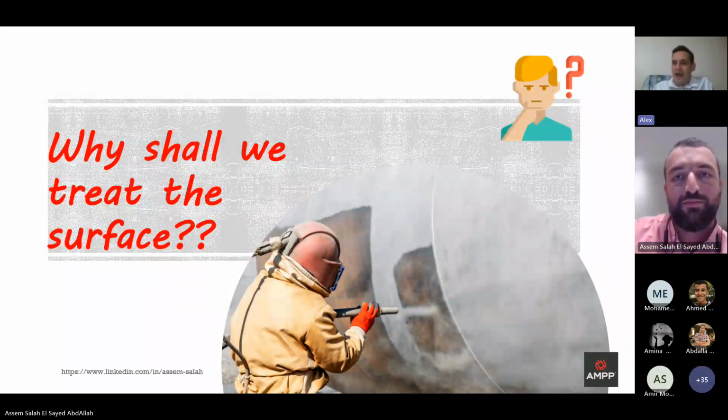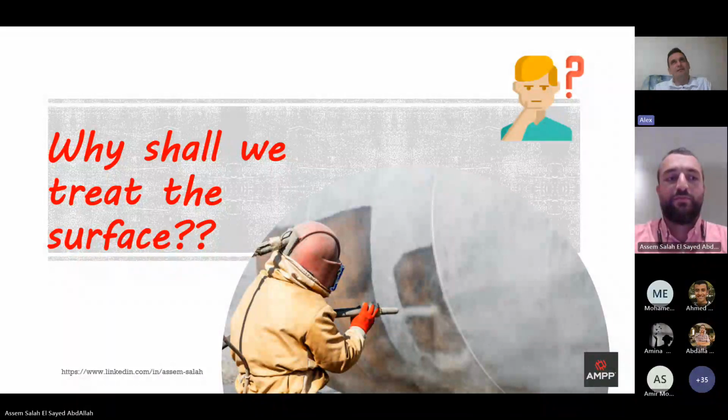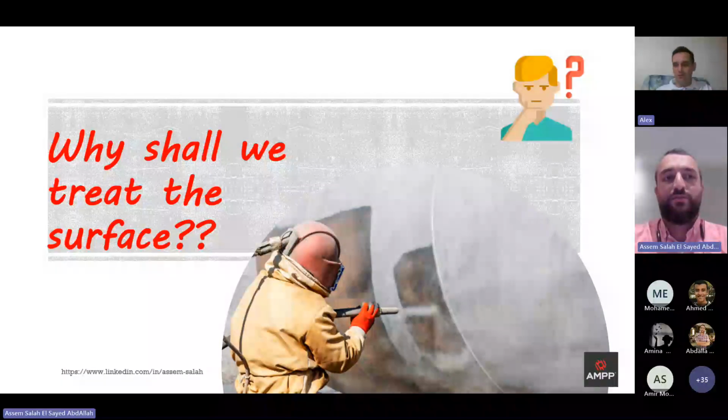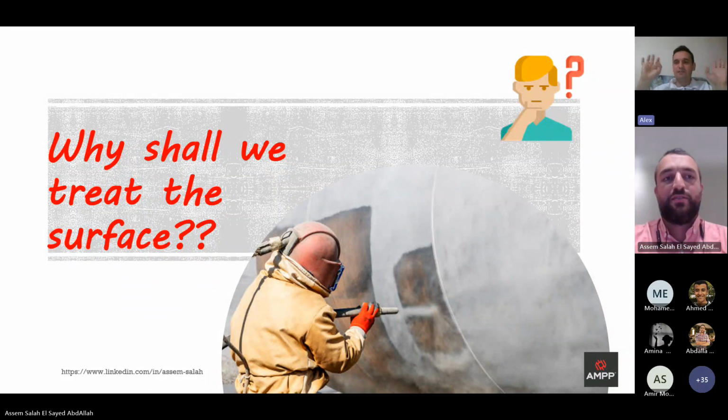Of course, if I have a possibility to do proper surface preparation, the price of coatings or the brand of the material you use is not as important. While if you do not do any preparation at all, the best coating will not protect your metal structure in a proper way. Exactly, I agree with you.